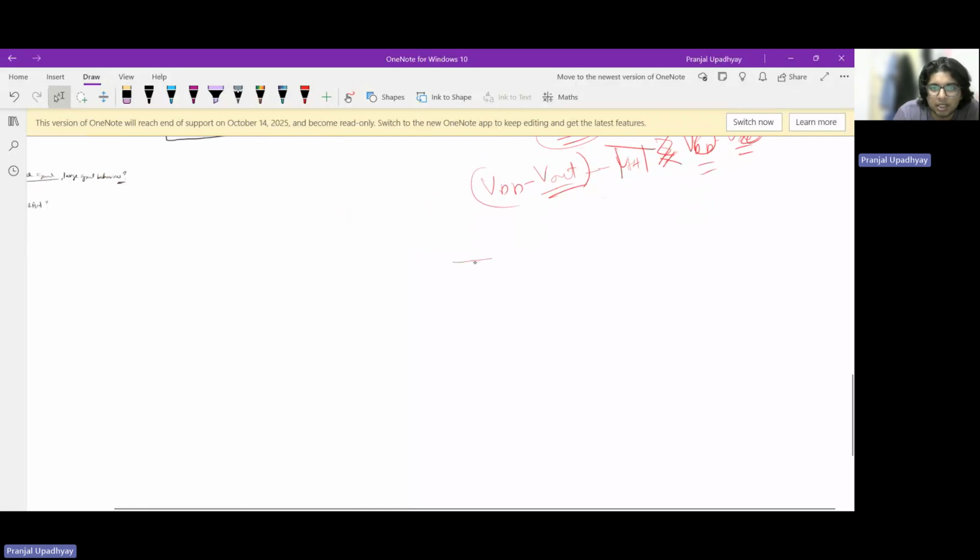So let us just say that we have a diode connected PMOS load and I have some circuit over here and I am sensing my output over here. So the fundamental limit to the output swing here will be imposed by what? Since this device is always in saturation, it can either be always on or off. And we can understand that this device will become off if Vout, or the gate voltage value, increases quite a lot, right?